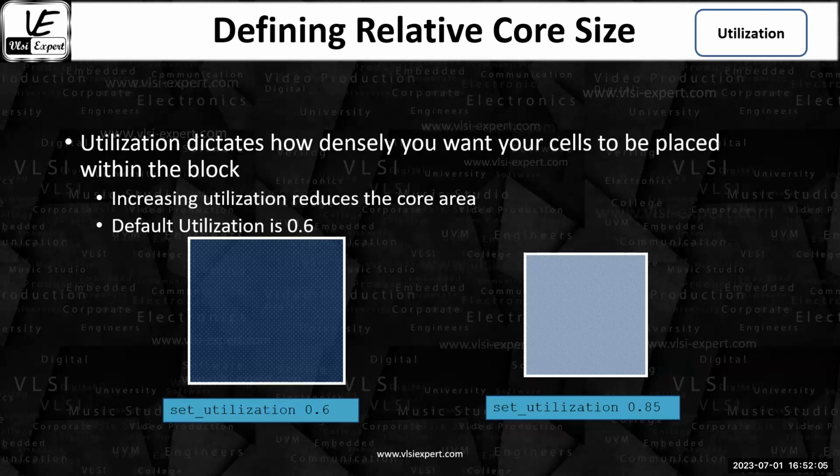So that's the reason, when you define the core size, there are two things. First, you have decided the aspect ratio. Then after the logic synthesis, whatever the gate counts are, using the physical information where their size is given, you will calculate the exact size. Then you will use it as a part of the utilization. You will say, okay, it's going to take only 70%.